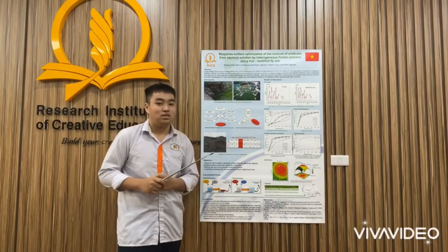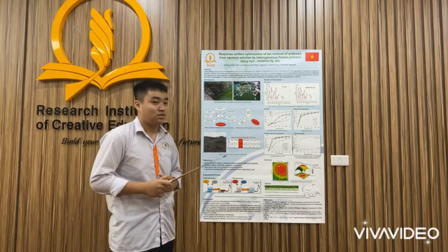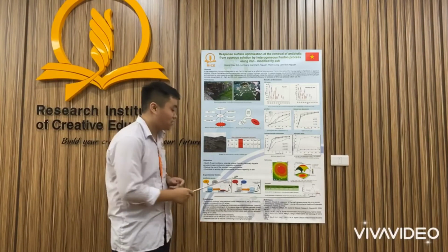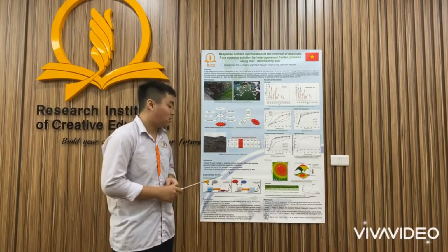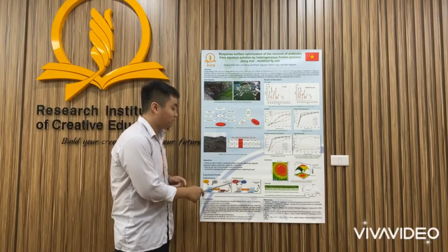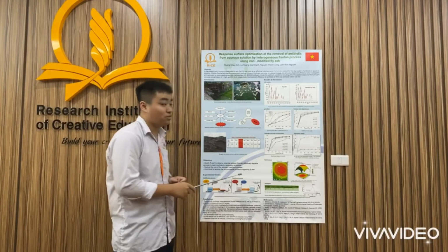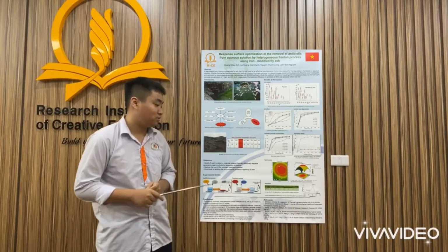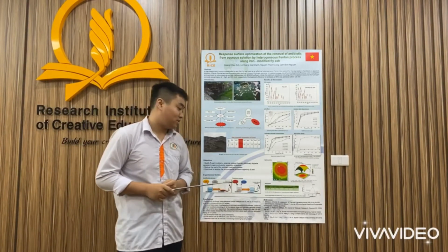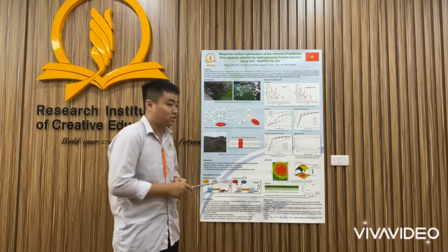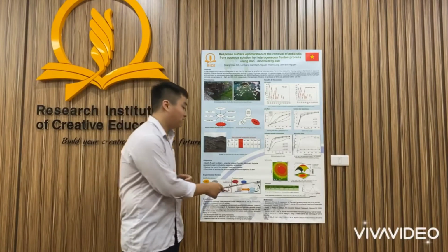2. Degradation of pollutant. First, the wastewater containing pollutant was adjusted in pH. Then, the mixture of catalyst and hydrogen peroxide was added into the wastewater during the mixing to start the treatment process. At the suitable time, the wastewater was sampled for analysis and determination of treatment efficiency.